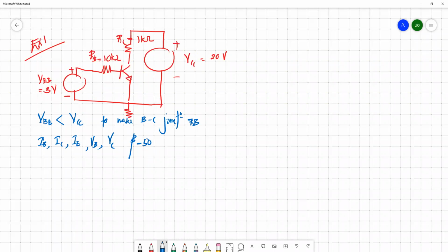So previously we identified two circuits. One is the input circuit, the other one is the output circuit. So we have two more relationships: IE equals IC plus IB, and IC equals beta times IB. These are well-known expressions you can use anytime. Other than these two equations, the rest of the equations are circuit specific, so it depends on the circuit you are referring to. You can use Kirchhoff current law and voltage law, and apply those fundamental formulas to the input circuit and output circuit to evaluate input and output separately.